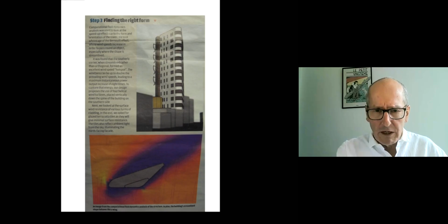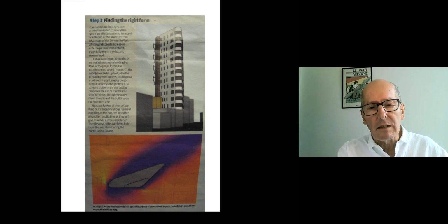Nevertheless, this is a nice little project because these architects realised they had a site that had a particular shape, already a little bit like an aeroplane wing, where the prevailing wind as it passed around the site, if they built a tower, which they did, would, if you like, amplify. Therefore, if they put a string of, in this case, helical wind turbines on the leading edge, they would be likely to turn more rapidly. So I think that is quite a nice use of gaining energy from the wind.